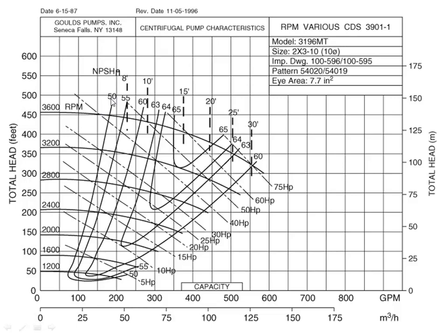The next thing I want to point out are these curves, 50, 55, 60. These are efficiency curves. You can find out the relationship between the energy that's going into the pump and the energy that it's providing to the water by looking at what location you're on in terms of a certain flow rate and a certain pump head that's being provided. You can find out how efficient it is. And that would give you an idea of the electrical requirements that may be needed.